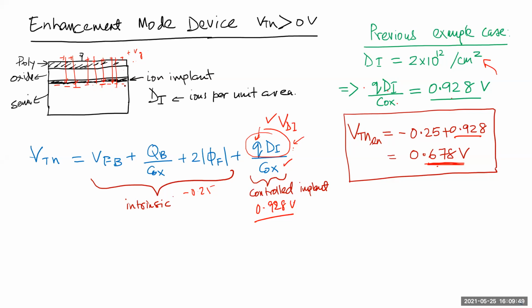If you guys remember yesterday when I was showing you the CMOS processing flow, towards the end you saw where it says VT adjustment, right? So it takes your diffusion mask and does this ion implantation to do VT adjustment under the gate. So before you form the poly, you do this adjustment first and then form the poly, because if you form the poly first, then you won't have this ion implantation, right?